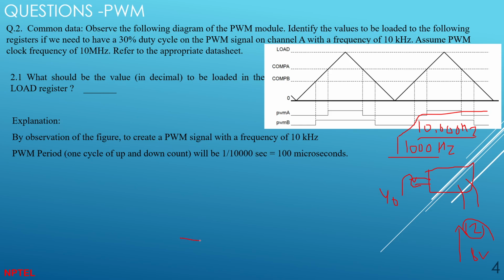So what we do is use this PWM signal, and we change the duty cycle. What is PWM? Pulse width modulation. Say this is 50%, with 5 volt and 0 volt levels. When you run at 100,000 hertz and send the signal to this part, it will interpret it as a half signal, because it's a 50% duty cycle, right?